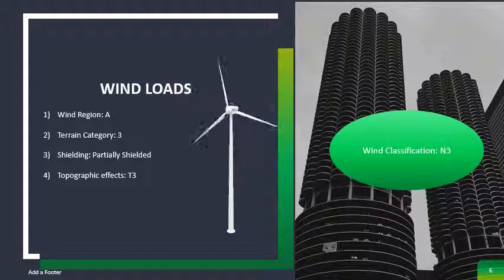The last force to be considered is the wind load. The first step of calculating the wind loads is to discern a number of variables to discover what wind class our project will fall in. The variables themselves were given in the assignment handouts but will otherwise need to be ascertained for ourselves. Our wind region for this project was A. This is the lowest wind speed of the four regions, and this is a non-cyclonic region.